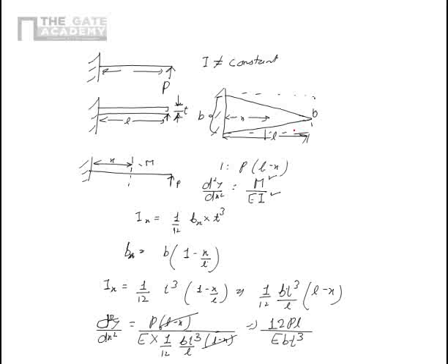This is a very important problem in wing design, where the deflection normally is not the main criterion. It is basically the mass or the weight of the aircraft which is more important there. Obviously, we cannot have a deflection which is too high also. So we go to a trade-off by seeing what is the deflection which we get compared to the mass which we have for the wing, and we reduce the mass to as low a value as possible, keeping the deflection also in check. But the way they solve is exactly this way only.